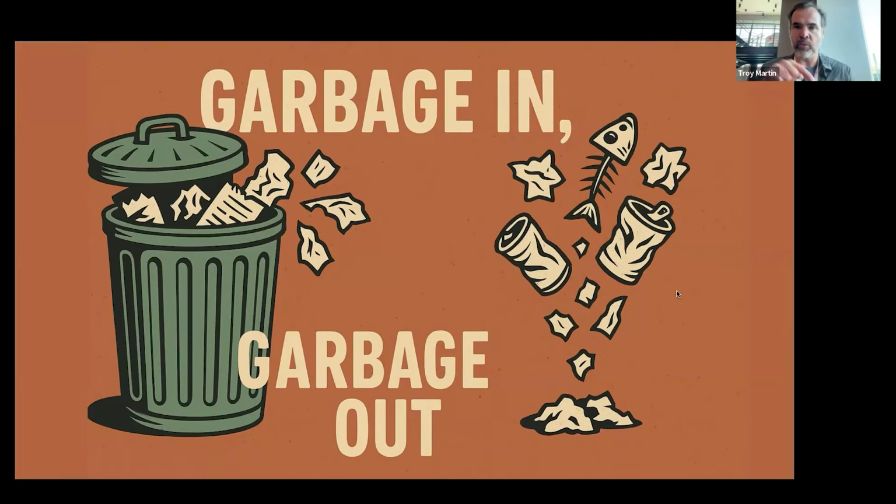I just click and pause where I'm standing. I haven't ended my continuous survey path; I've just clicked because I stopped walking. Once that door is open, I take one step into that room, click again because I'm about to stop, and wait for the door to close behind me. So I let it close or I slide it, whatever the office scenario is. Once that door is closed, I'll walk around to where the chair and the desk are, and I'll stand there, pausing again for about 5 seconds. So throughout the entire continuous survey, I haven't ended that survey. I've just made longer pauses to give more time to collect that data.